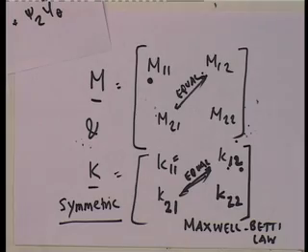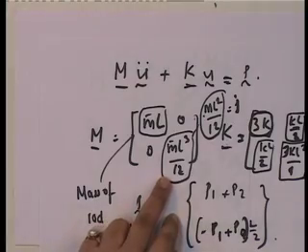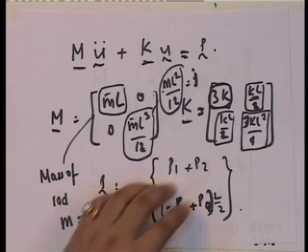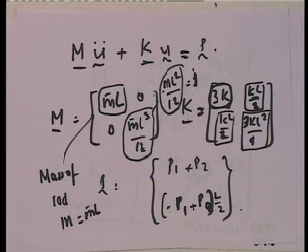Now the point becomes, look, I have already developed the equations of motion. What do the equations of motion look like? Well, I saw that, didn't I? Mass was equal to this, stiffness was equal to this, corresponding to u x and u theta defined at the degrees of freedom at the center point.